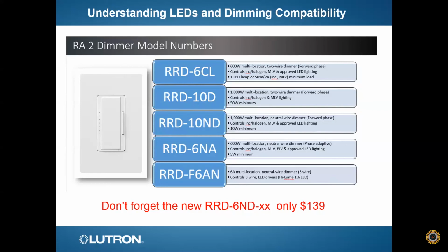The low-end trim would be, again, you're having a problem once you get down to about 10%, so you can set the low-end trim on that dimmer to 10%, so when you push the dimming button on it to dim that all the way down, it'll only dim that fixture or that bulb down to 10%, and that's the max at the bottom. The high-end trim you can set if you've got a really bright LED and you don't necessarily need the entire lumen output of it. You can set the high-end trim so that when you turn it on, it only comes on to 90% or 80% or something like that. But check out that new feature in the app. That'll save you some headaches there too.